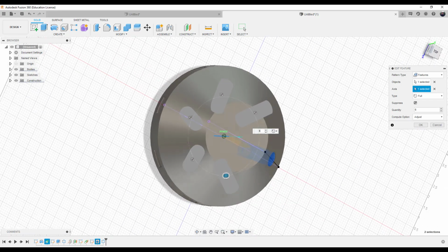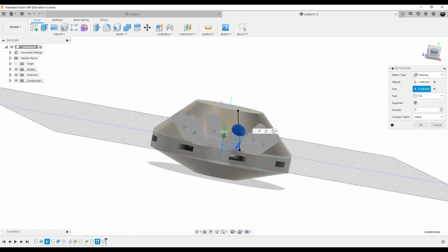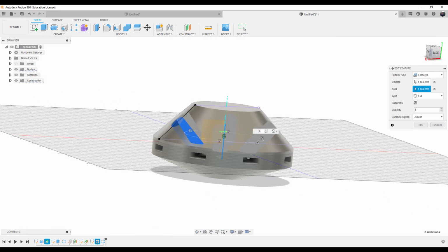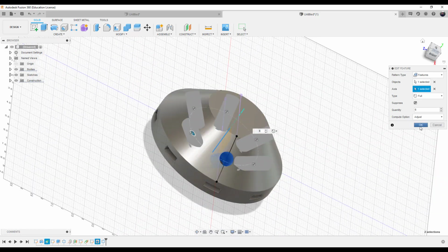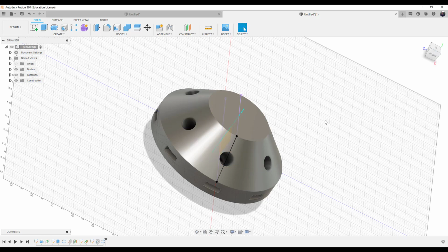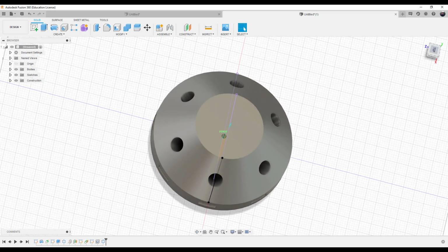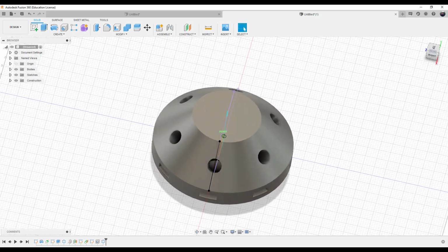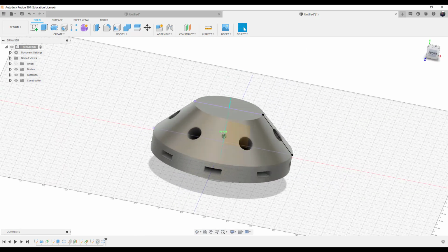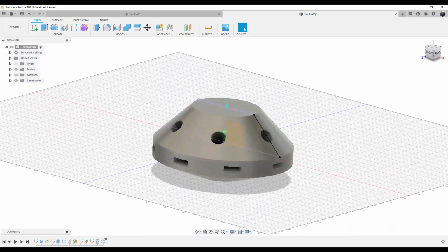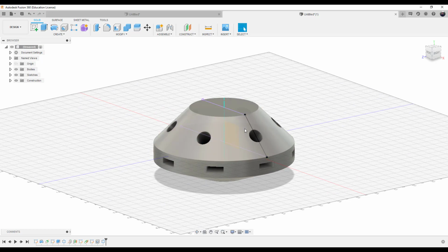Because if I look at it, maybe not. Maybe that's going to work. All right, let's check it. Compute option. Distance is full. And choose OK. Bingo. So there are 2 axes. The one axis is slightly off from the center line as the second axis. So we had to use the correct axis to project that. But you can see that these holes are perpendicular to that angled surface, which is our goal.